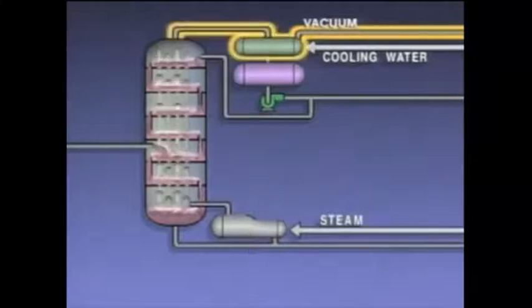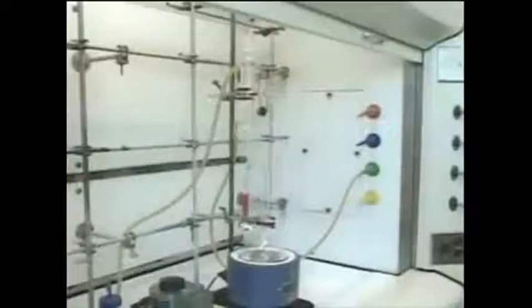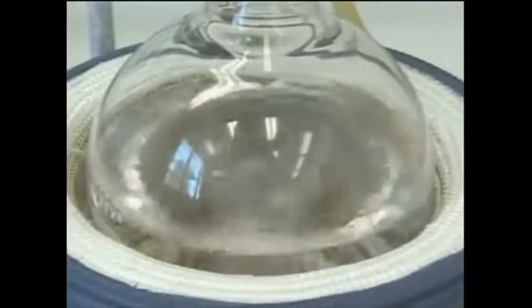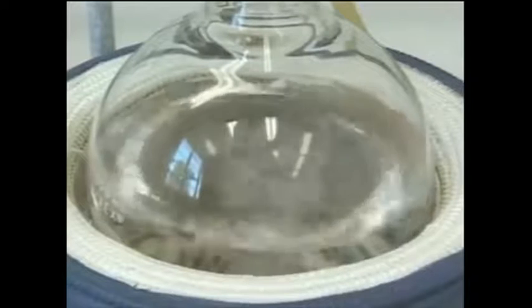Even if more heat is applied and all of the mixture vaporizes, the vapor composition remains the same. One way to separate an azeotropic mixture is to use a solvent. The solvent is a substance that, when combined with the azeotropic mixture, allows the separation of components to take place. Another way to separate an azeotropic mixture is to use two distillation towers in a special arrangement.